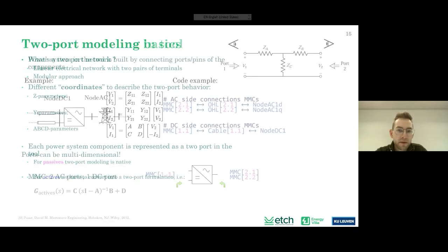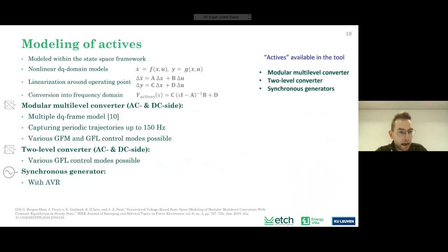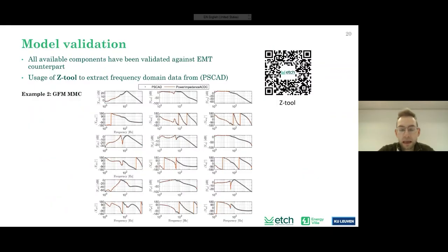For the validation, to validate the analytical model power impedance against PSCAD, I used the averaged model of the grid forming asset. But I can also tell you I did this validation also with a switched model in PSCAD, and I also got a very good result. I wouldn't say the match is a little bit different, but I'm bold to say that you can also get a very good match with a switched model.